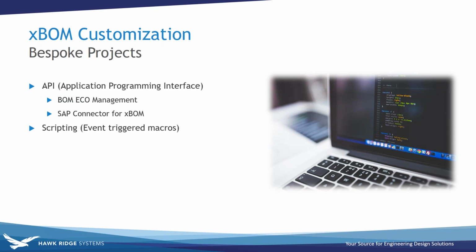So this one was interesting in that we've got BOM compare inside PDM, and you've got BOM compare inside XBOM. What we don't have is API access to BOM compare in PDM, right? So we'd actually have to recreate the compare feature from scratch in order to do that directly from the PDM data. Whereas the BOM compare output that we saw in XBOM is directly available inside XBOM's API.